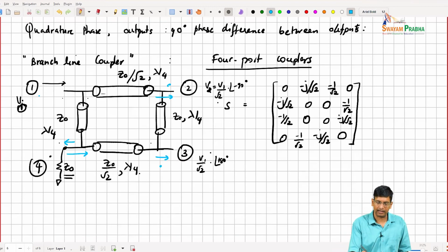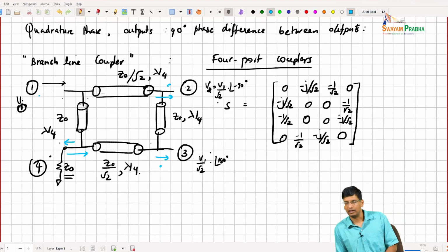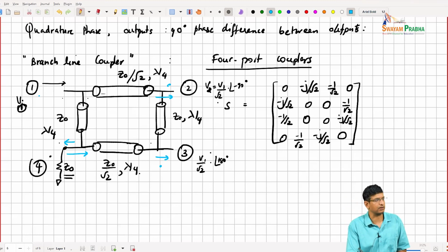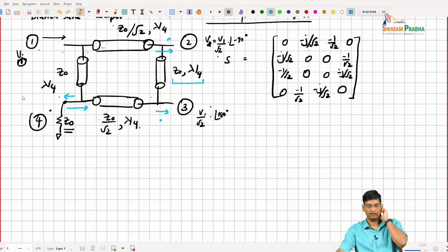And again, if you want to build lumped equivalents of it, we've already seen a pi section that gives you lambda over 4 at a frequency and a Z naught, right? So you change the values of L in order to get this other section, change these two sections, which are a smaller characteristic impedance. But you can build this using inductors as well, and we will look at implementation that even further reduces that area more.